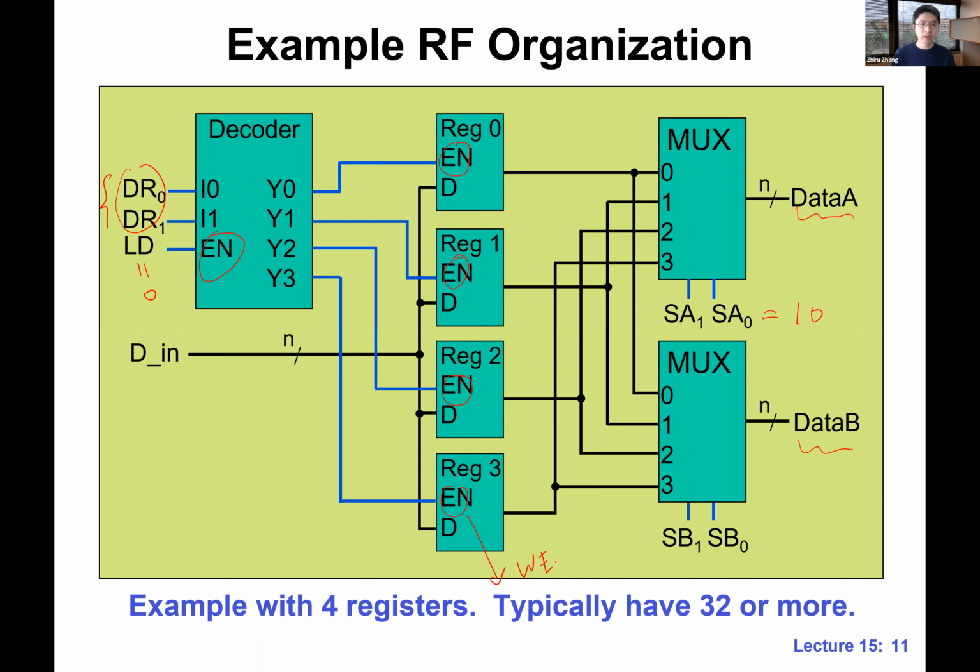Basically, hold means that we are not writing. So in that example, all we are doing is we just turn off the clock. That's it, we gate the clock. Something like this. This is a clock signal. All we are doing is we gate the clock, we just put a 0 here. This is one way to build an enable for a register. Hopefully this makes sense, because DFF is an edge sensitive device. All we need to do is to gate the clock to turn off the edge.